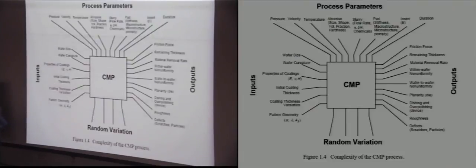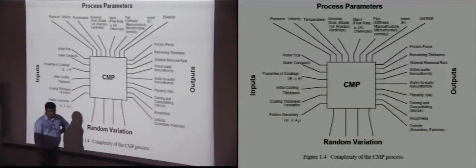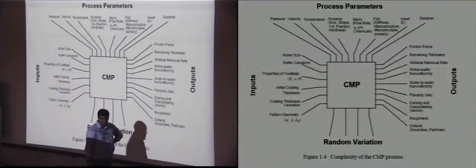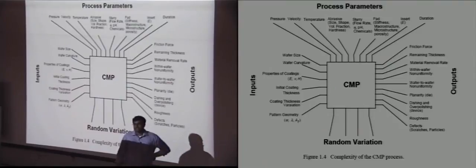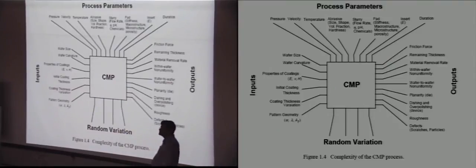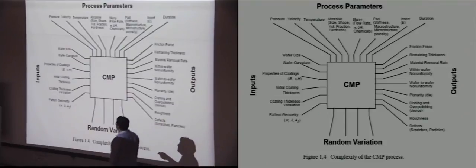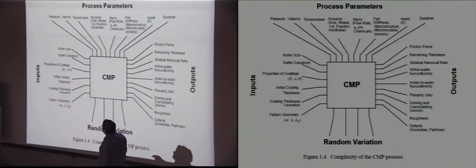Okay. So chemical mechanical polishing is sometimes called the dark art because there are too many factors that come into consideration. So every process needs to be individually optimized. Every profile, depending on the material systems, etc., has to be very carefully considered. The factors brought in by the wafer itself include the size of the wafer. A 6-inch wafer and an 8-inch wafer and a 4-inch wafer will be different.